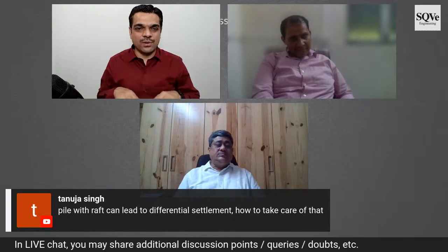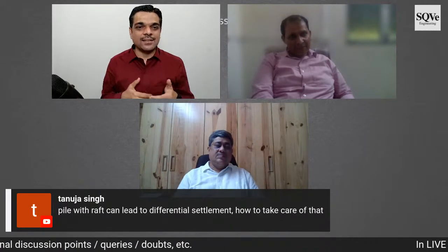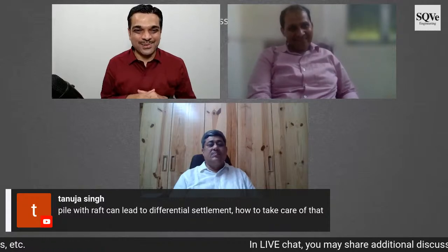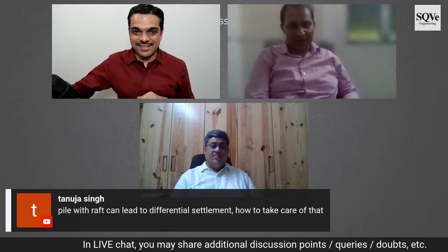Yeah, and Sandeep ji, I am also thinking that for this area also, close interface is required between the geotechnical and structural engineer. Let's say certain foundations are provided. Now, the settlement value given in the soil report is considering only one type of foundation. But if the structure is sitting on different types of foundation with different sizes altogether, then I think close interface is required instead of just merely picking a value from the soil report, right? Yeah, because what happens is that, like the example I shared in the presentation,